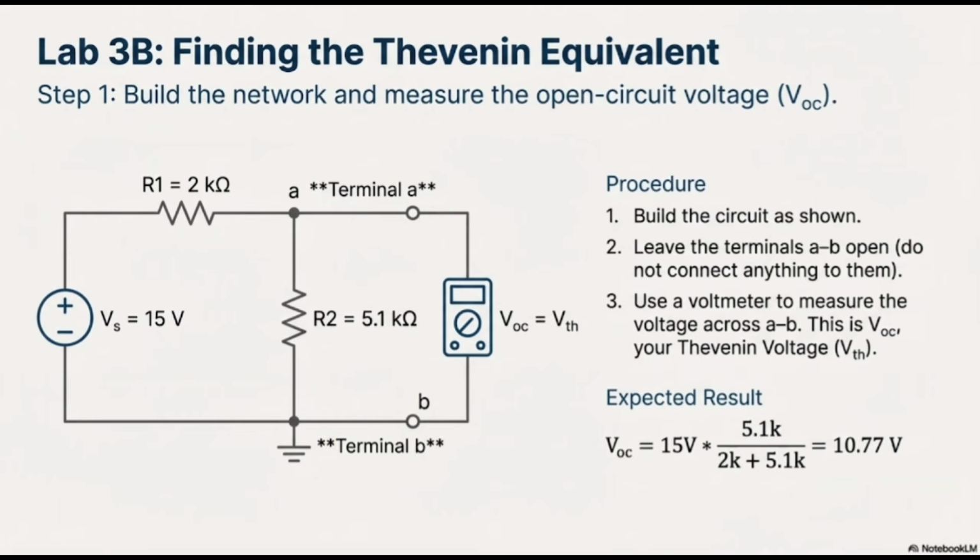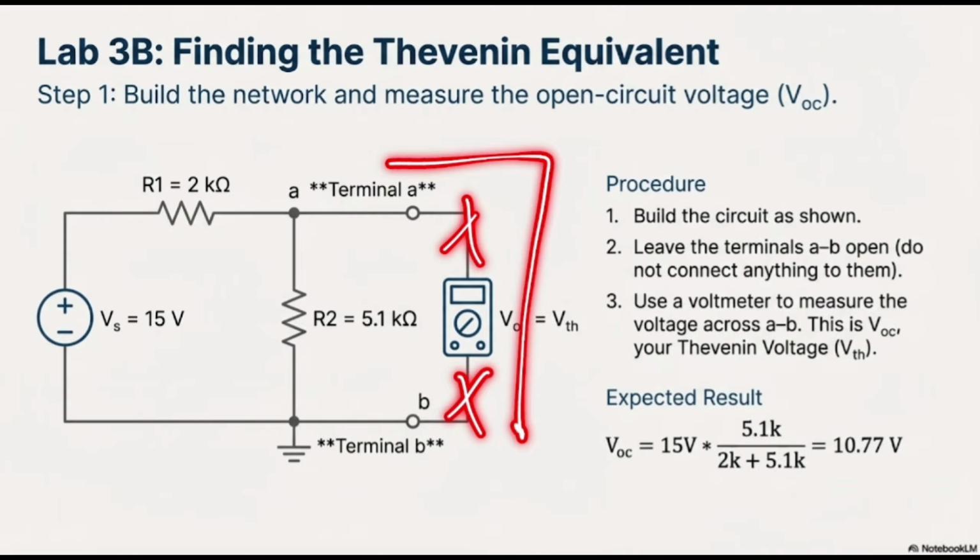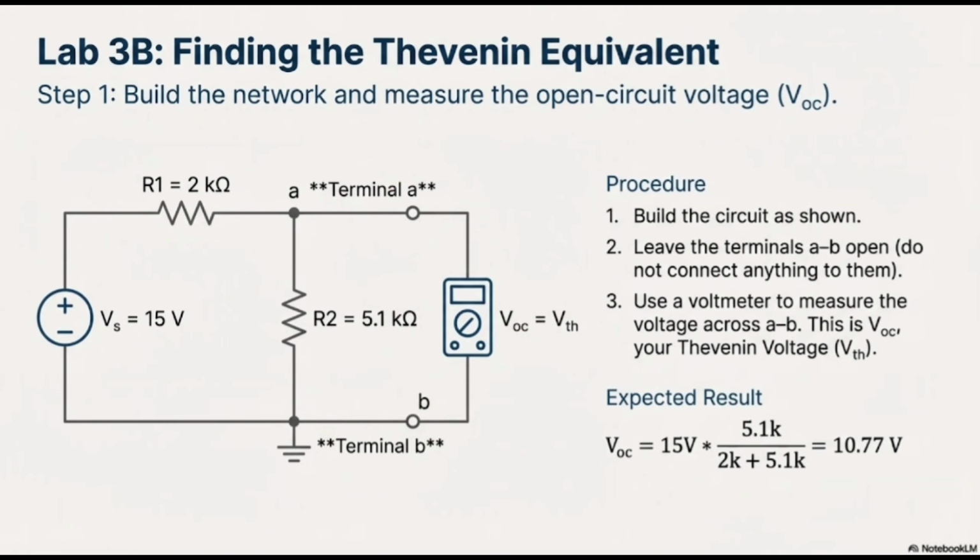If I make this open circuit, it means that no current goes through it. So that branch is just open circuit, nothing. For finding the voltage you can see through AB, the only thing you have to do is find the voltage of R2. We know that if we have two resistances and one voltage source, I can either use the voltage divider or simply find the current that goes through this mesh, and then find the voltage drop across R2.